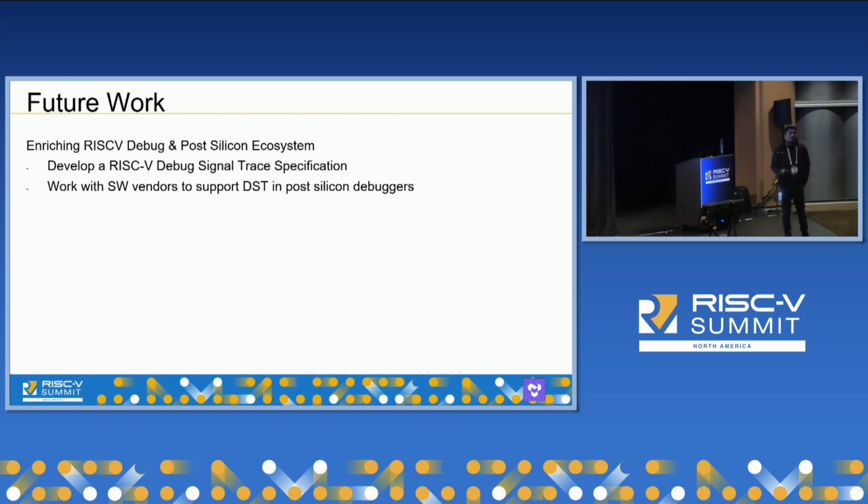The normal use case of debug bus traffic is medium traffic, and with our compression, we are able to reduce the memory footprint by 30%, right? So yeah, it's a long-winded answer, but if you want, I can share specific numbers with you, but it all depends upon multiple factors. Do contact me for specific calculations. Yeah, great question.